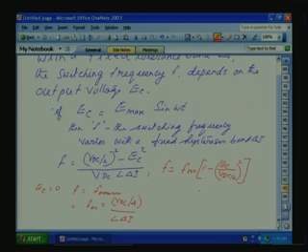So, why is this introduction brought? If EC varies sinusoidally, then F will vary, the frequency will vary around Fm. EC can go both positive and negative. So, this switching frequency F will be modulated around a value, and the maximum value is Fm. Okay.